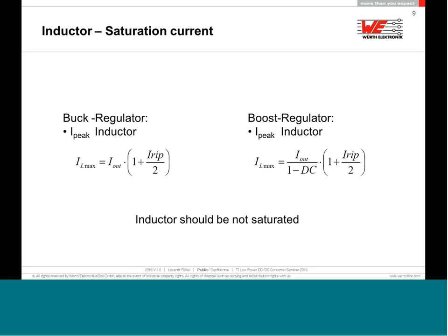How do you choose an inductor so that it is not saturated? Again, for the maximum current in this case, I would say at this value the inductor should have no saturation at all. If you have the space, of course, sometimes it's a space problem and you have to make some compromise. But I would recommend that if you use these very simplified formulas, you can have no trouble choosing the right inductance.